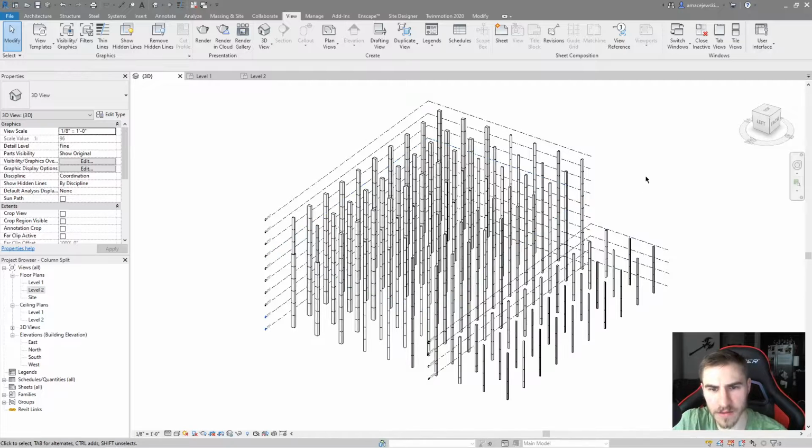So what we're looking at here is nothing special, a basic template, but I've got a bunch of columns here. I don't have a full building, but I have a full building of columns. These columns in a way represent the full building, because the structure has to do with the levels and grids. We have all of our grids in place over these columns, and the levels are associated as well, and we can really begin to define the extents of everything that we need when it comes to datums in Revit and in this project.